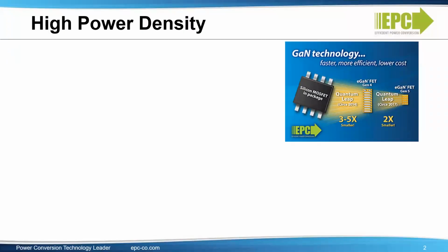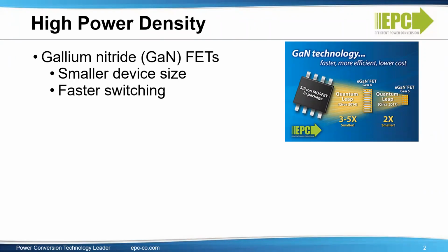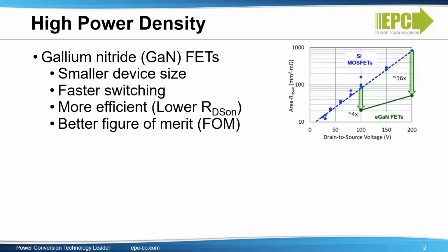Before we go over to the online calculator, I would like to talk a bit about the background of the online thermal app. So as you may know, GaN devices have been gaining popularity over silicon MOSFETs as more powerful and more efficient alternatives. And that's due to a set of factors. GaN devices demonstrate exceptional performance since they are smaller, they switch faster, and have a lower on resistance, and thus are more efficient than their silicon counterparts. Moreover, GaN, having a higher band gap, is also more capable of high voltage switching and is thus a better candidate for high power applications.